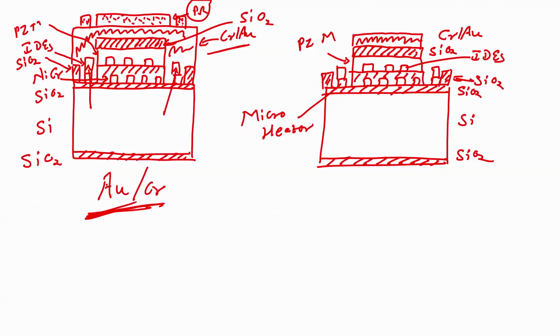So, you can draw a schematic similar to schematic 1, and when you perform lithography, you can mask the area with the help of photoresist, so that when you dip the wafer in chrome and gold etchant, the chrome and gold will get etched only in the region which is not protected by photoresist.